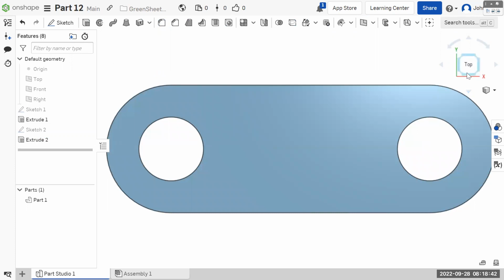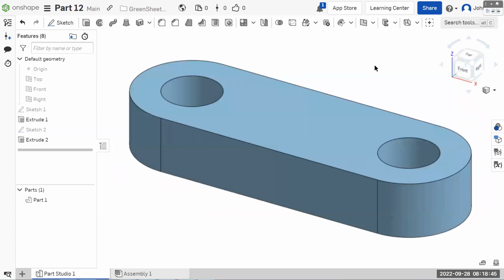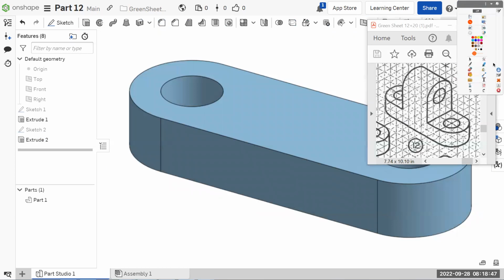All right, and then the other part we'll do the same way we did the last one, where we sort of have its footprint, which its footprint is, come on, pen. Sorry. Its footprint is 4 this way and 4 this way, which is the entire depth front to back. But the difference now is this rectangle is just going to kind of be floating. So we are going to need to dimension its distance from a known point, which the one side should be 2 from our center point of our other circle.